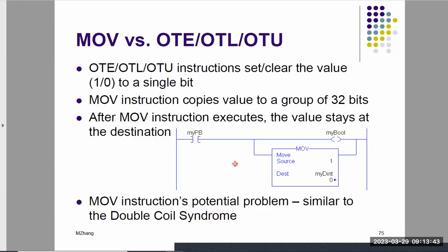On top of that, does anybody remember the pump speed? You can change the pump speed, right? The pump is driven by a motor. Of course we use a Boolean tag to turn it on and off, to energize and de-energize the motor. But once you energize it, we want to control the speed. You set up 50% speed or 75% of the maximum.